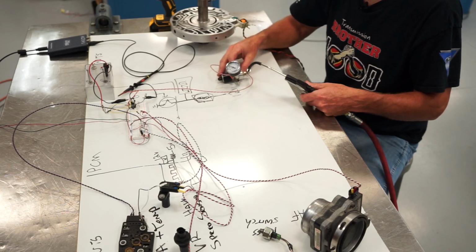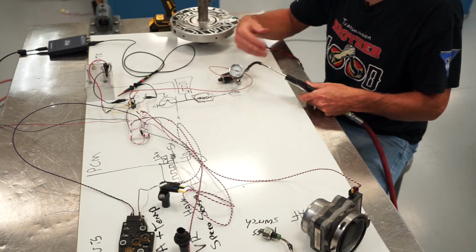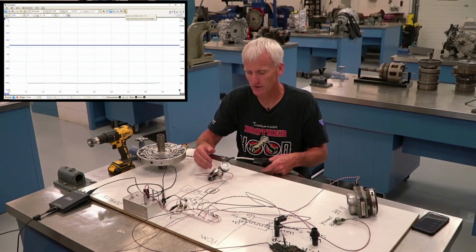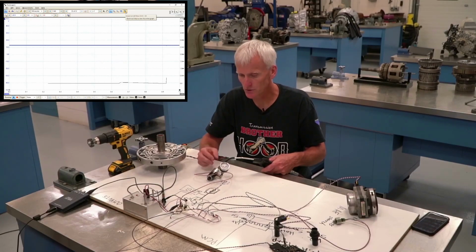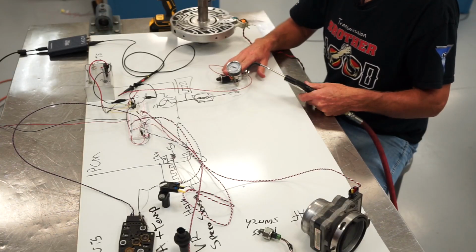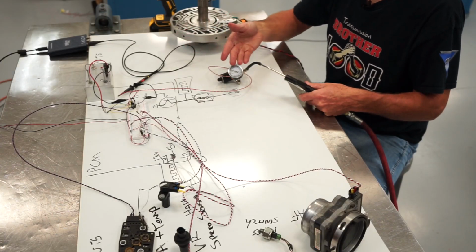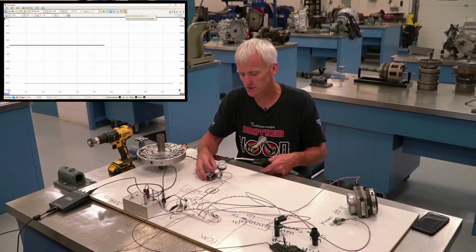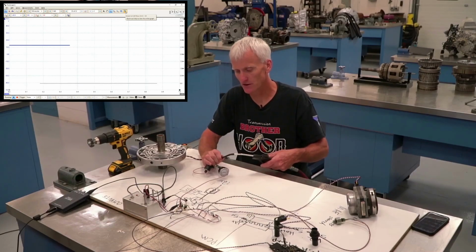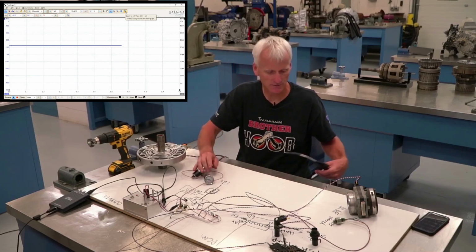So with this thing electrically off, it passes pretty much everything through it. It doesn't trap any pressure in there. And then they energize it. The more they energize it, the more hydraulic fluid gets passed through, so into the hydraulic circuit. That's just one way they control it. So this right here is an output, and it's a variable output. They change the output of this solenoid to change the amount of pressure that it finds through it. One of the outputs that we've got, it's called a PWM or a linear type solenoid.